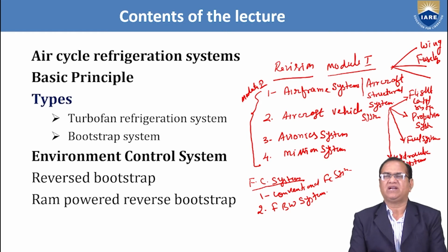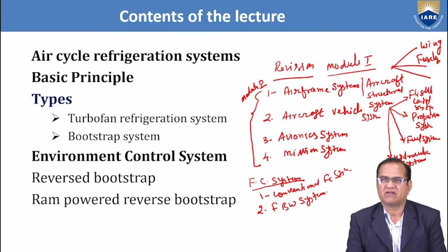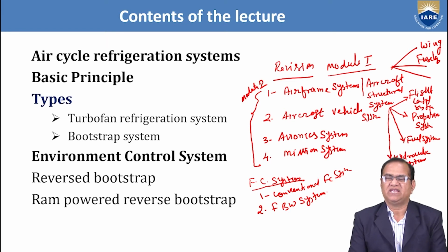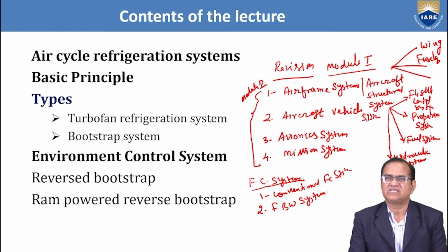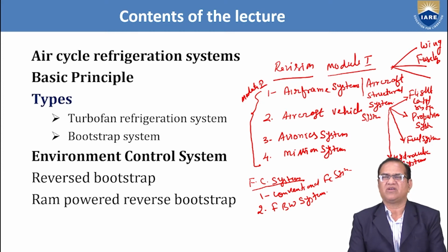But if you see the conventional flight control system, it is a hydraulic or hydromechanical device. In that, the pilot has to push the rod and the different control yokes, control sticks, and the mechanical linkages by pulleys, wires and all. It is transmitted to the respective flight control surfaces. In this way, the flight control is achieved. This is not so good, and nowadays it is mostly obsolete, and most aircraft are now using fly-by-wire.